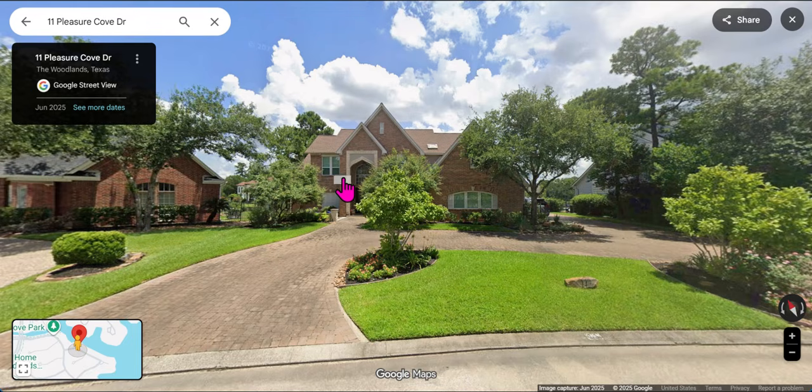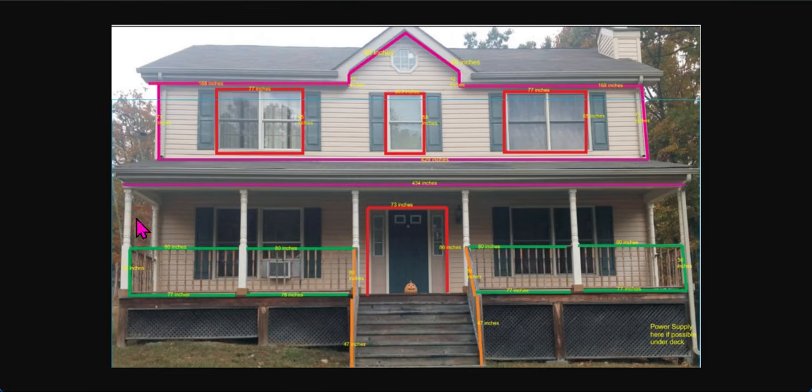Now, how do you know what pixel density to put in there within xLights? Well, that all starts with measurements. You'll need to get out and actually measure your house. Now, I do not recommend using apps. I recommend actually getting a tape measure out and measuring those distances. You will need to do that at some point.